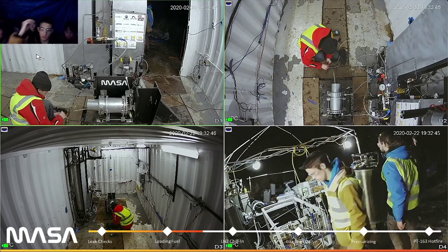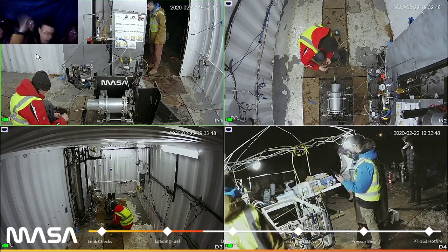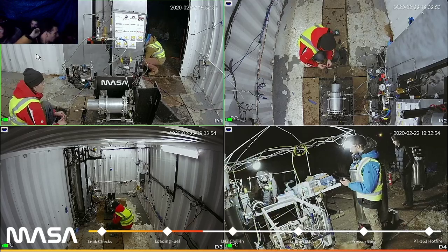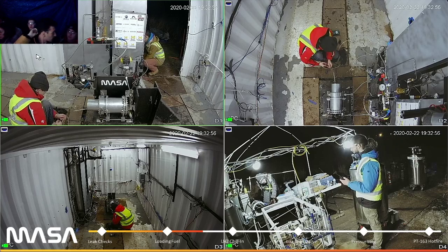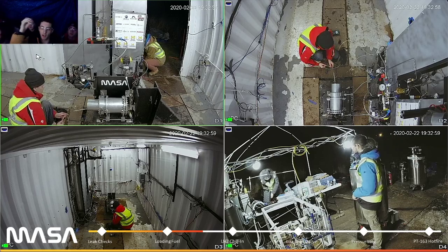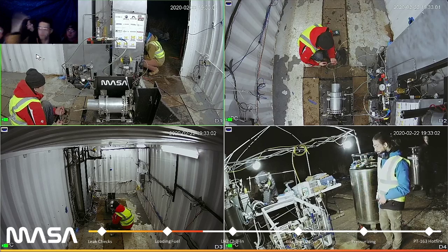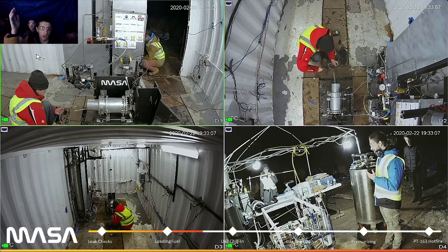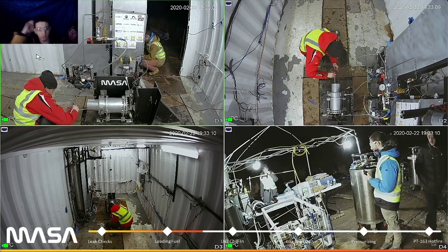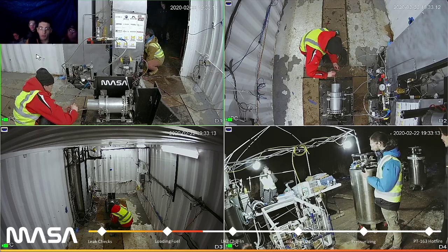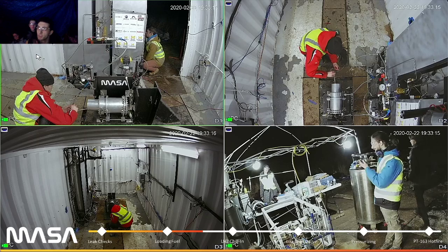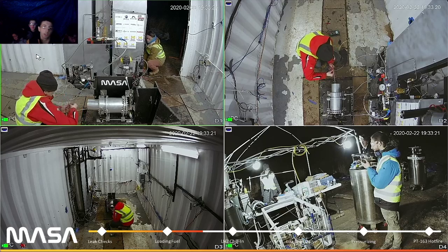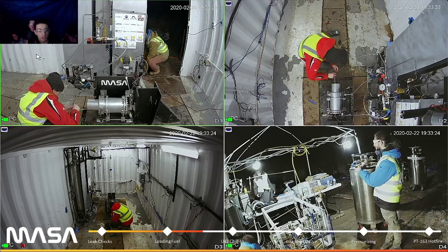We took apart the valve that was the leaky valve, and we realized that there were actually some pretty glaring issues inside of it. So we found a new one. We had another valve of the exact same type in our workspace. We made sure that one worked, so we switched it out. We performed a cold flow last weekend, and that determined that the valve is good and should be good for hot fire. That was really one of the major problems that caused us to abort the test last time.